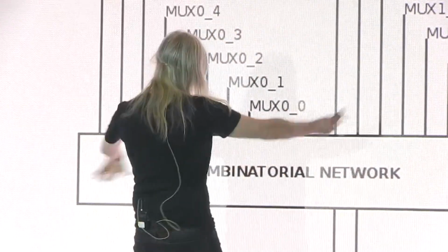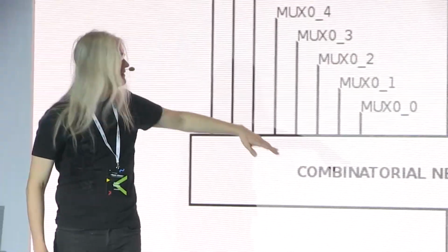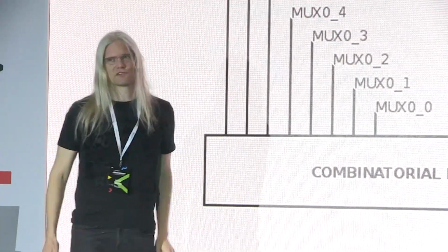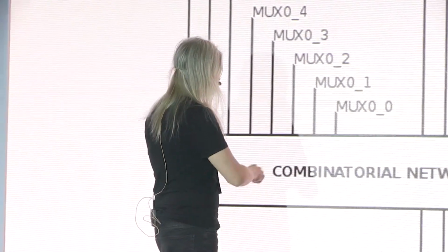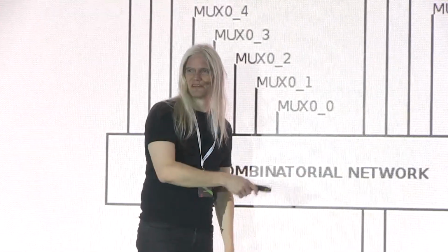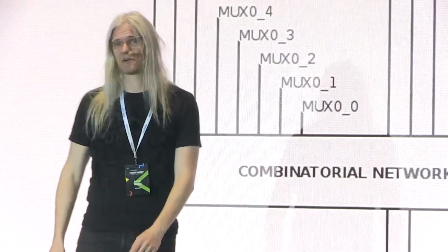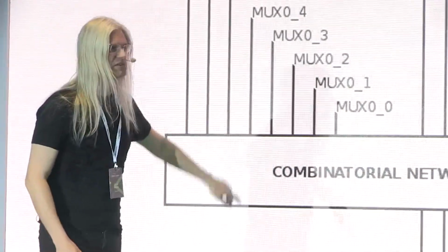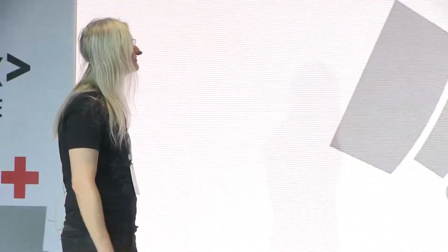And then there's all kinds of stuff going on here, which they have written in their VHDL, and out come all of these mux controls. And you can easily imagine, if there's a race in here, or something went wrong, what do we do? We spin a new ASIC. Not good. It's better to have it under software control. So these days, this kind of solution is highly unrecommended.